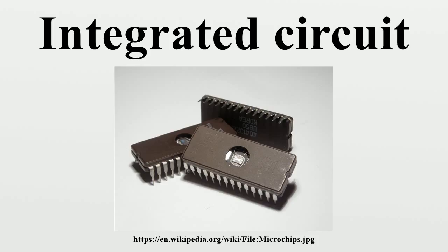VLSI, the final step in the development process, starting in the 1980s and continuing through the present, was very large-scale integration. The development started with hundreds of thousands of transistors in the early 1980s, and continues beyond several billion transistors as of 2009. Multiple developments were required to achieve this increased density. Manufacturers moved to smaller design rules and cleaner fabrication facilities, so that they could make chips with more transistors and maintain adequate yield. The path of process improvements was summarized by the International Technology Roadmap for Semiconductors.